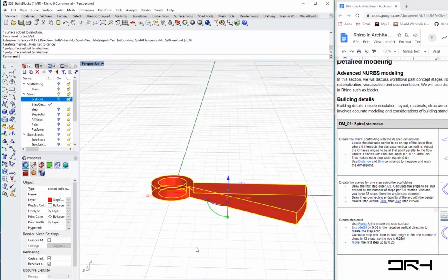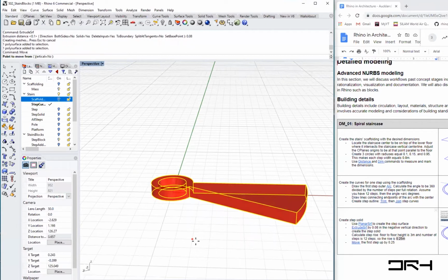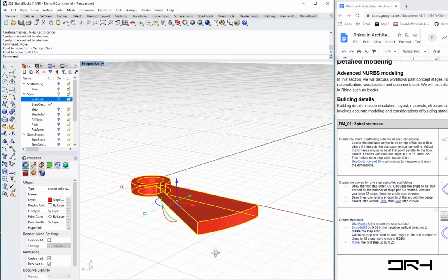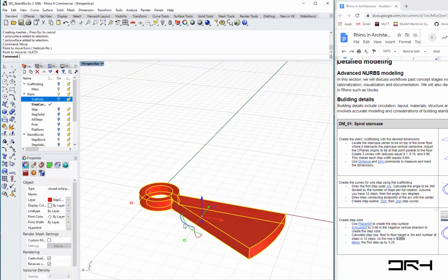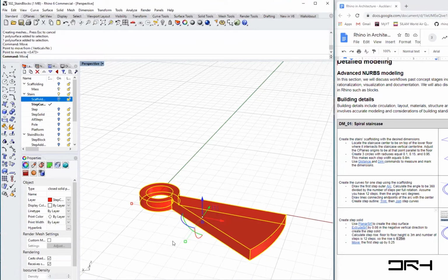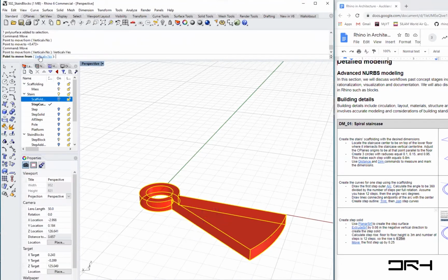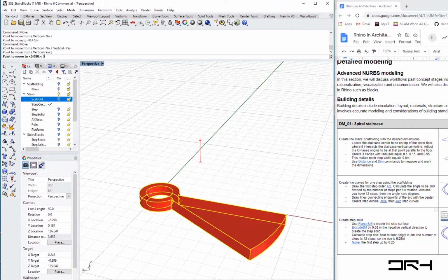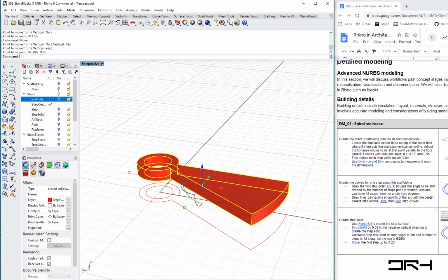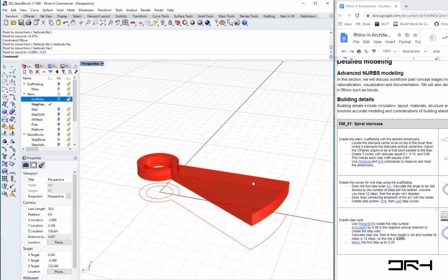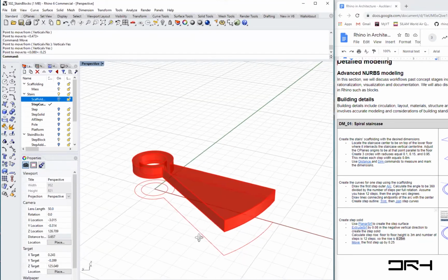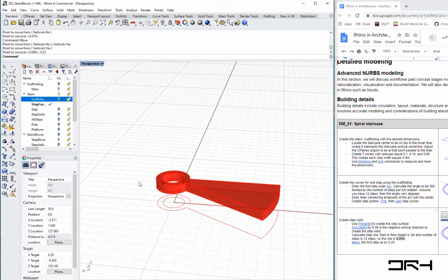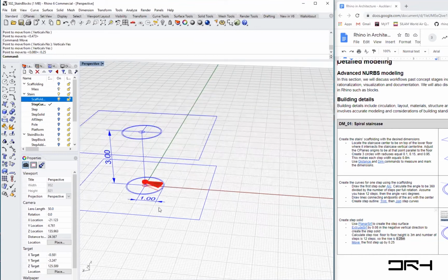So the first, and if this was the floor plan, let me first move it downwards so I can exactly move it up, because this is going to be my first step. And let's say the C plane is aligned with the step. I can move it vertical from any point by 0.25. So that my first step will be basically elevated by 0.25 meters. Okay. If I turn on the scaffolding, as you can see, that's kind of the first step that I have.